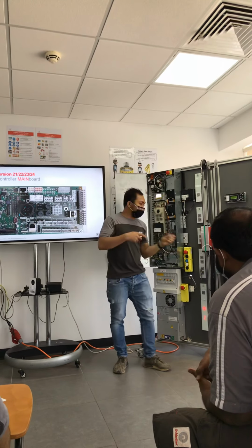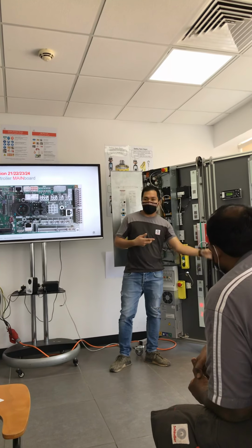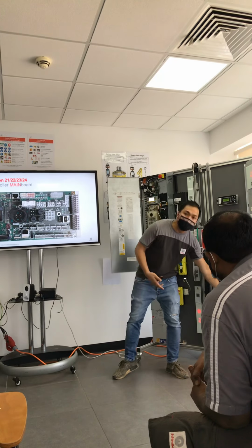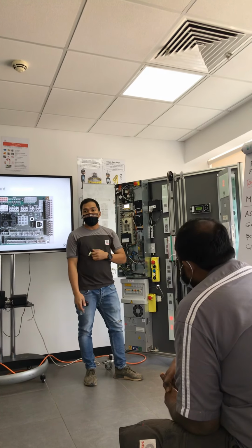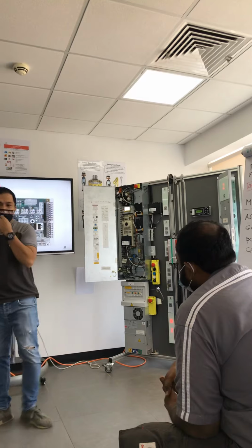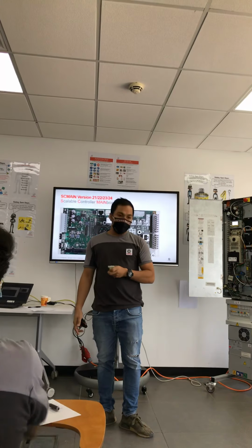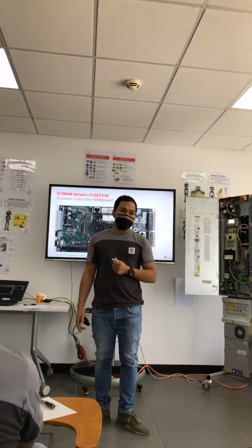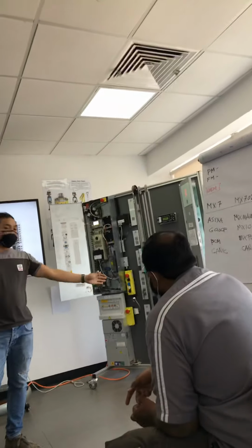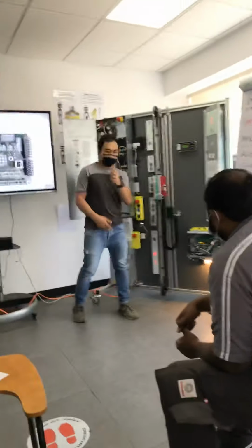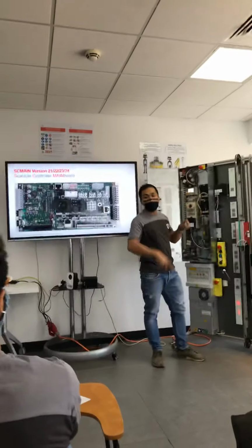So it means I terminate it here, I terminate my car. For example, I have a problem with my PCBs. What's the benefit of it? It's not only used during installation. On maintenance, I may have a problem with my PCBs, so maybe some inputs and outputs of your car it doesn't recognize. So what happened? I can isolate this. I will terminate this one by just putting it here, put installation mode, and then I can run my elevator.